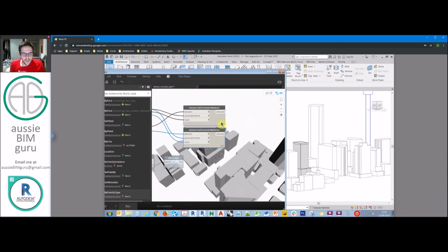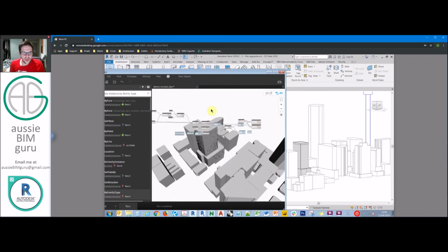Okay, and from there we'll set our lacing to longest just to make sure that it applies to the longest length that it can. Okay, so that should work, but what I might do is actually just set this up for Dynamo Player and run this via Dynamo Player instead. It'll take a little bit longer, so I'll probably skip ahead when I run it that way.